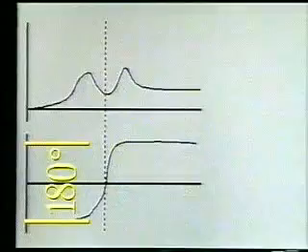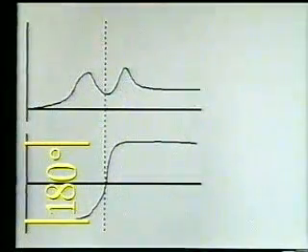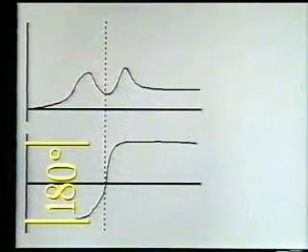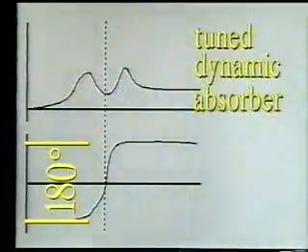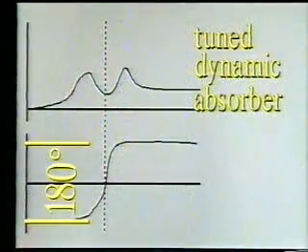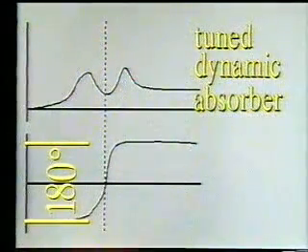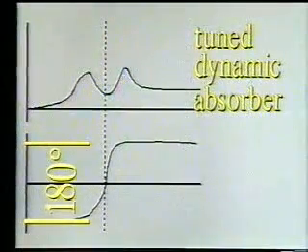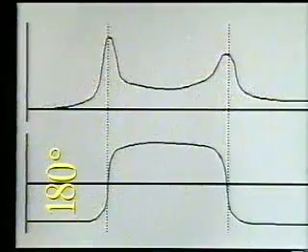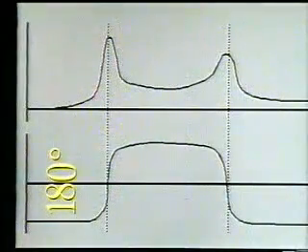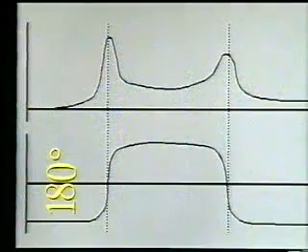However, the amplitude versus RPM data does not have an increase at that frequency, but may even have a low area or hole. This indicates the presence of some mechanical damping, such as a tuned dynamic absorber. The dynamic absorber is designed to remove the vibration at a particular frequency, and this indicates it is doing a good job. When there are two phase shifts, it indicates there are two resonances in the system.